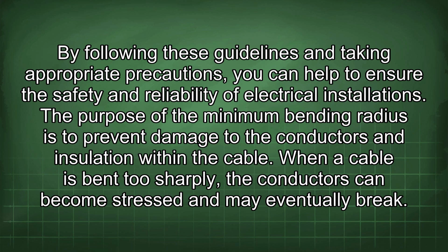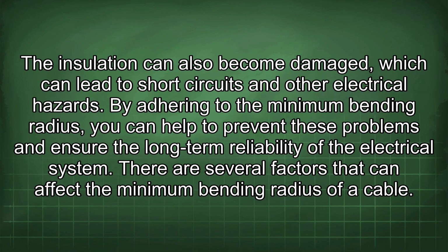The purpose of the minimum bending radius is to prevent damage to the conductors and insulation within the cable. When a cable is bent too sharply, the conductors can become stressed and may eventually break. The insulation can also become damaged, which can lead to short circuits and other electrical hazards. By adhering to the minimum bending radius, you can help to prevent these problems and ensure the long-term reliability of